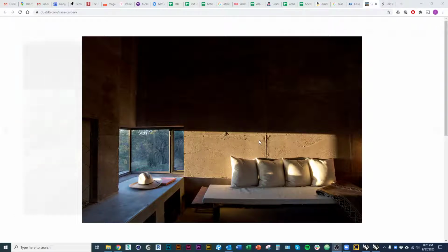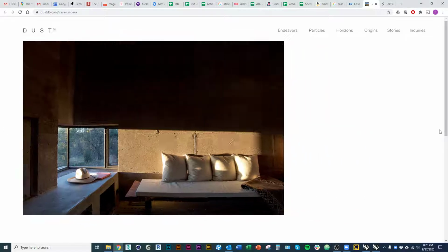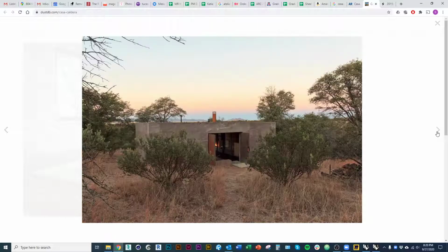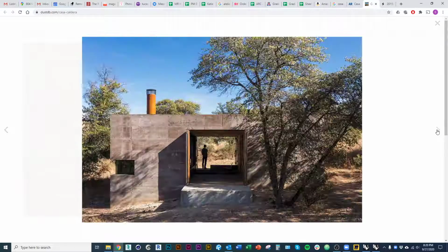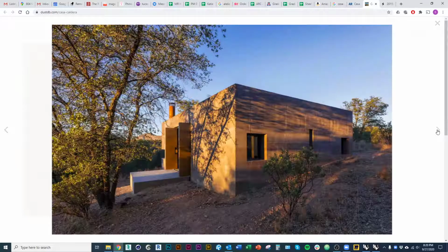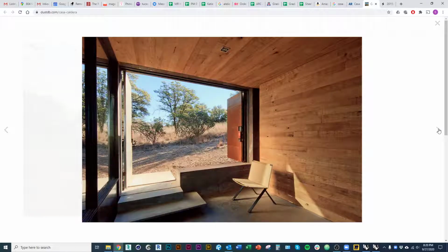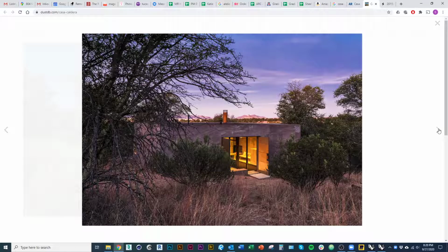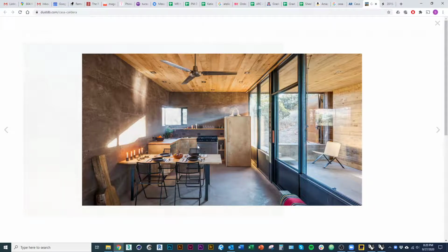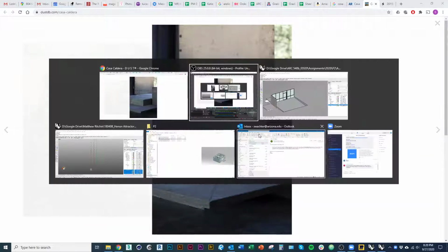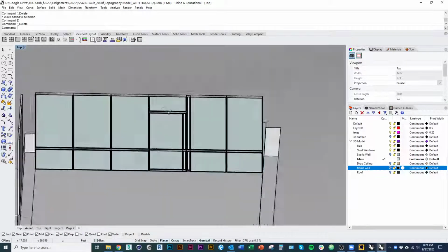Okay, so in this video I'm going to cover how to model a couple of the additional detailed things in the house. So things like the windows in the corners, some of the casework, and some of the framing for the doors, that kind of thing, and the chimney. We've already covered how to model the glass wall, the zag one, and casework. Oh, and then that concrete step as well. So starting off where we left last time,